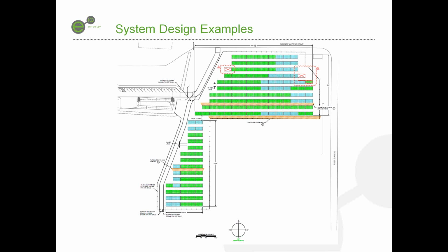Let's just kind of take you through what a site looks like. And you can kind of see here, this is a recent site that we did. The site was a megawatt in size. It was challenged from a geometric perspective because, as you can see, it's not really a perfect square. There were a lot of long runs that needed to be accommodated, runs that were probably longer than you would want to see for purposes of voltage drop and I²R losses.